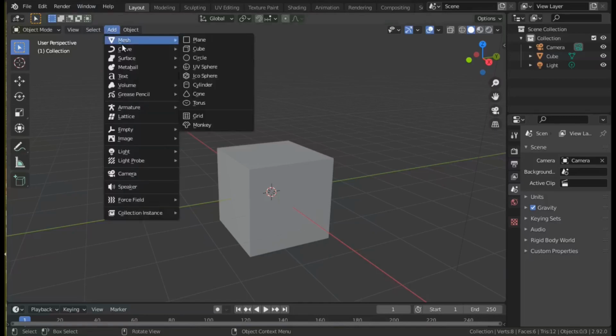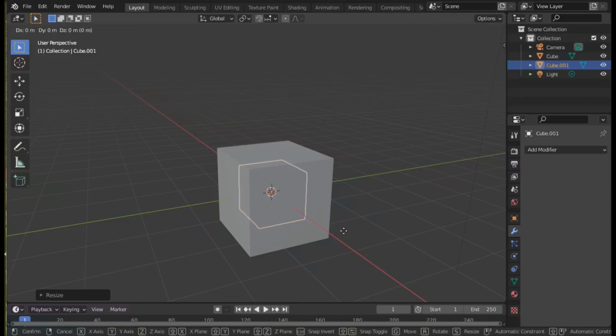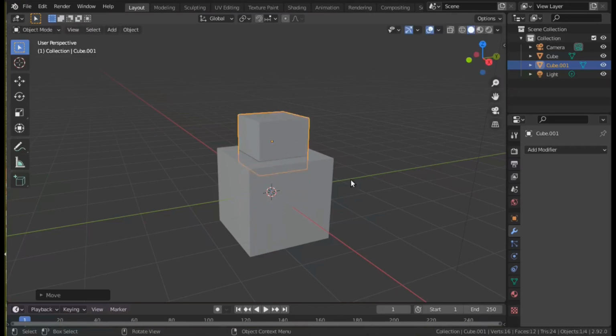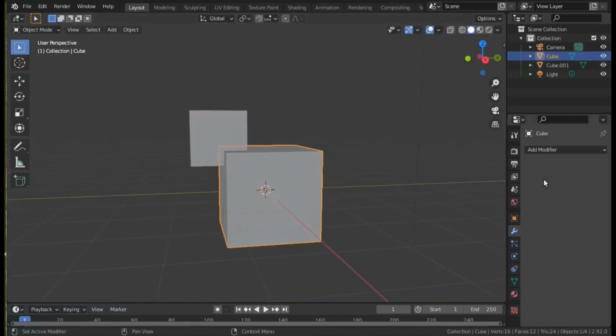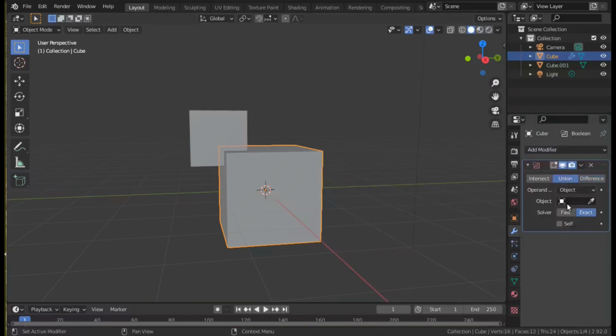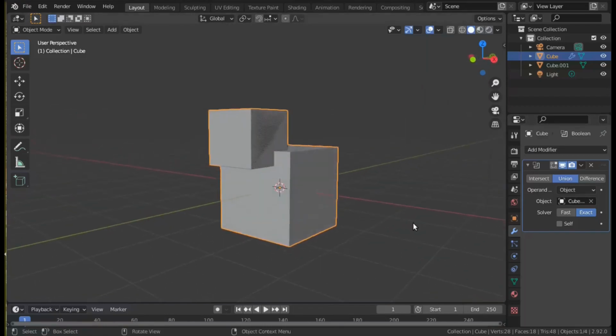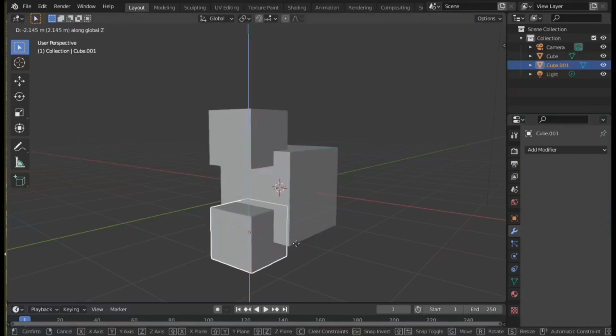We're going to look at a few more modifiers now. So to start with, we'll use the boolean modifier a few more times. Duplicate the start cube, scale it down, apply the boolean modifier with the small cube as target with union, apply it, and then scale the second cube a bit more so it's a different shape, but apply it twice more to make a strange model constructed from 4 cubes intersecting each other.